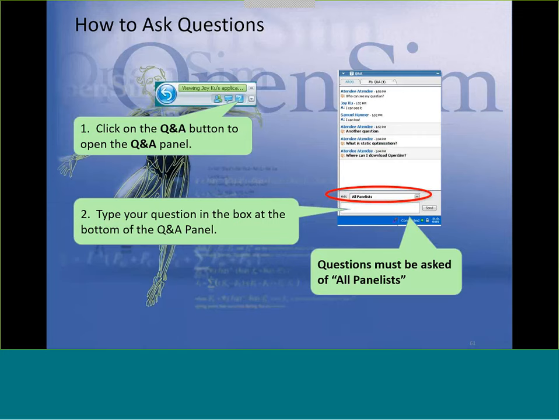That's a really good question. We find a lot in these types of problems that it's not a smooth objective function, and so there's a lot of local minima, there's a lot of spiky parts of the objective. The nice thing about CMA is that it doesn't explicitly use a derivative. So it's less likely to be caught in some of these local minima. Also, it's a stochastic optimizer, and so it chooses its population given a distribution. So it allows it to be more likely to get out of these local minima as well. And we found that that was really useful in solving our problem, and has also been useful in some other frameworks that we've seen, like from Tim Dorn and Jack Wong's work with walking and running.